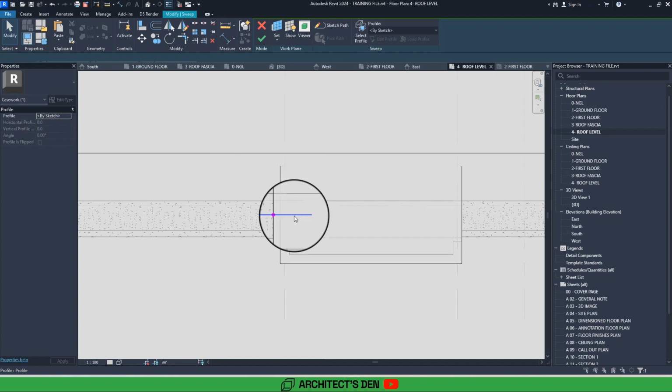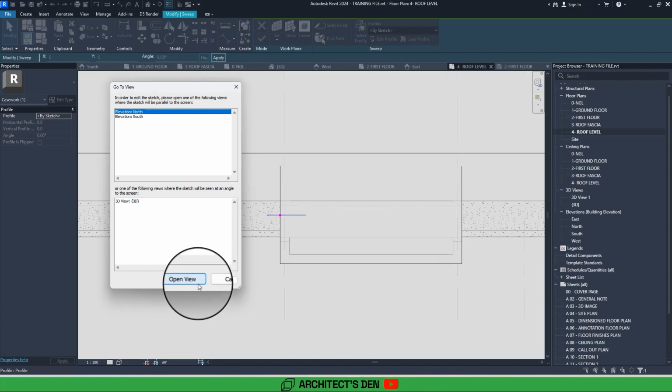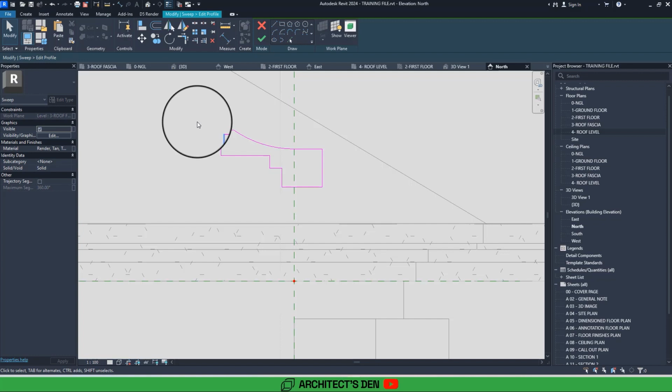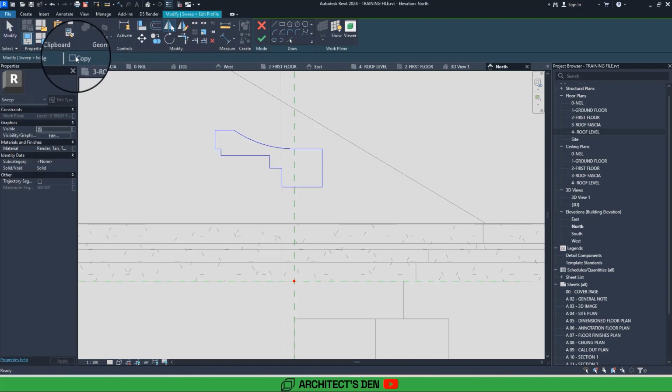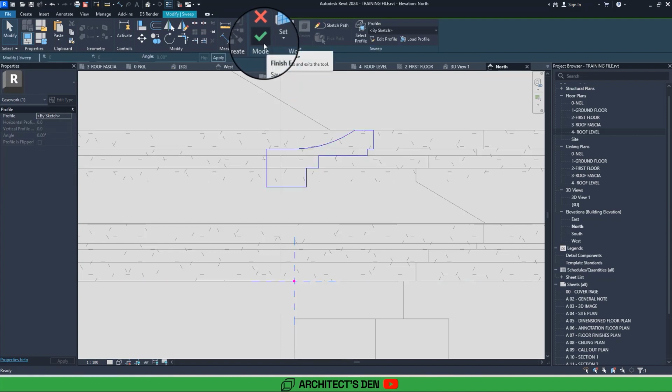So now when you do something like this, like copying a casework and you put in a new sketch path, you notice that sometimes it can flip. What I mean by flipping is that this profile will flip the wrong way. So you can select it, come to an elevation, and make sure copy is unchecked and flip it the right way. So you can just do that.